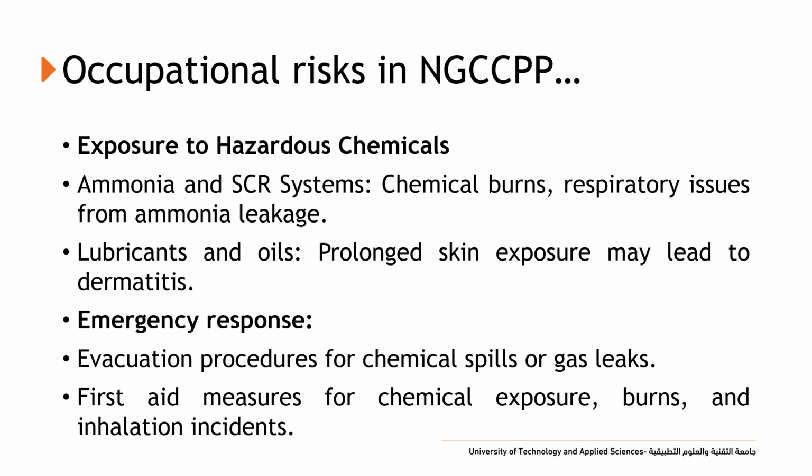So the next type is exposure to hazardous chemicals. As I told you, ammonia is used in SCR systems, selective catalytic reduction systems. It may lead to chemical burns and respiratory issues, and prolonged exposure of lubricants or oil on skin may lead to dermatitis, dermatological problems.